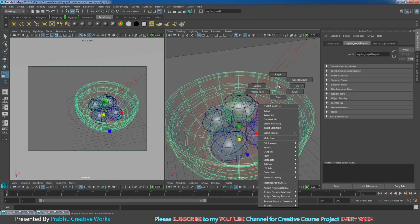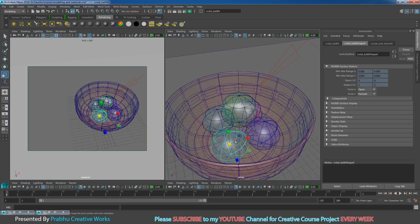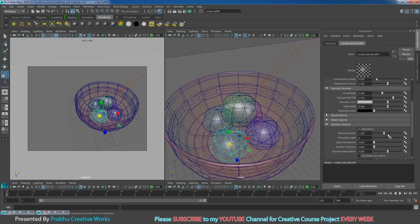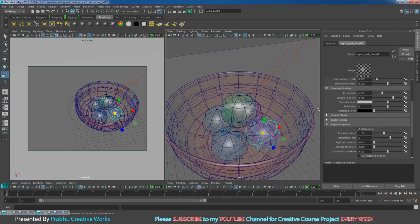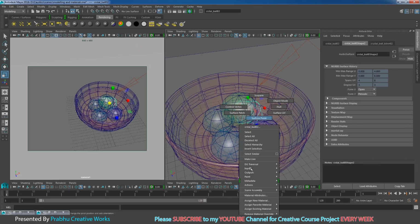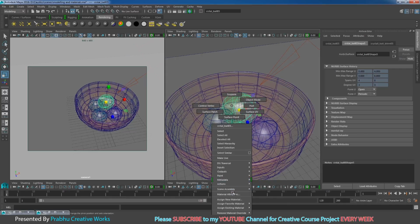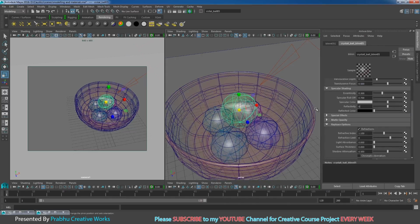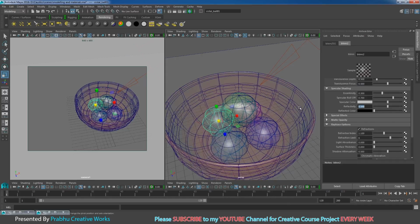So I will select this object, right click and choose material attributes. I want to reduce my reflectivity to 0.2. You want to do the same thing for all other objects: right click, choose material attributes, and set reflectivity to 0.2. Right click and choose material attributes and give 0.2.